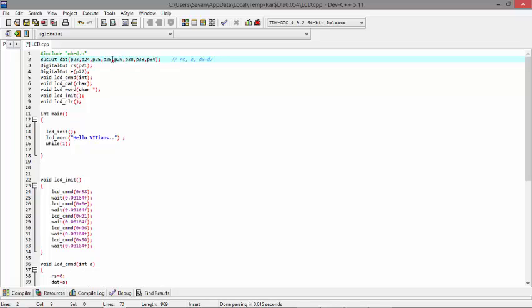In between, 27, 28 and 31 and 32 are used for I2C and USB, so I didn't use them. I'll just take another GPIO. That's it. And for another GPIO I defined RS and E, that is P21 and 22.